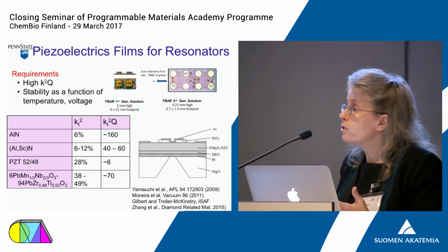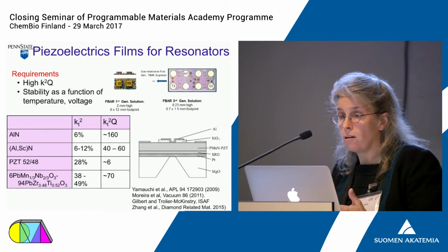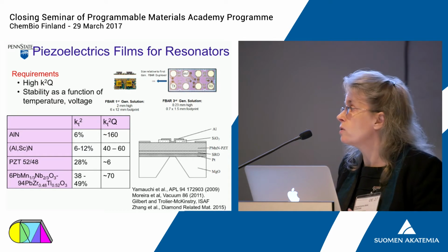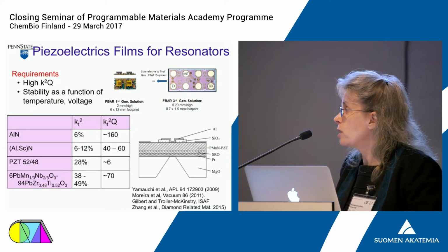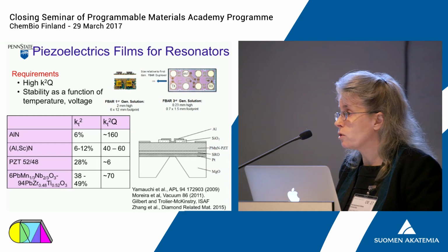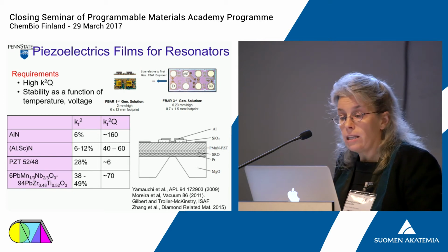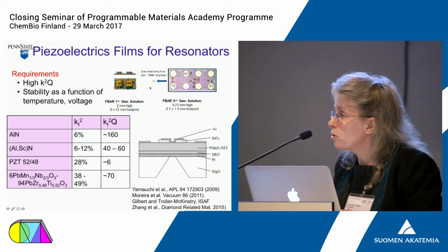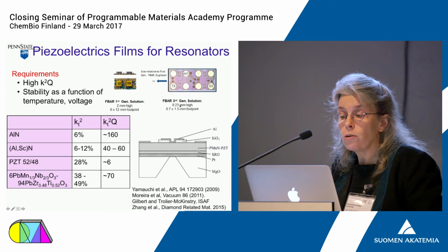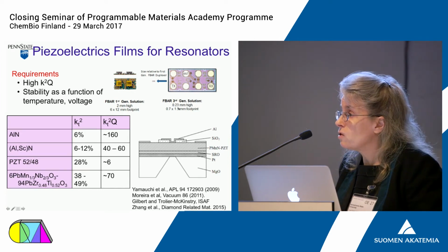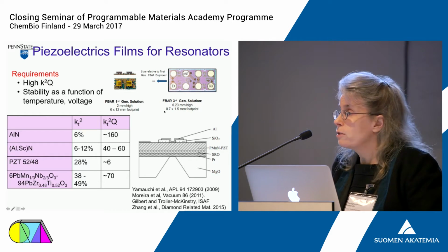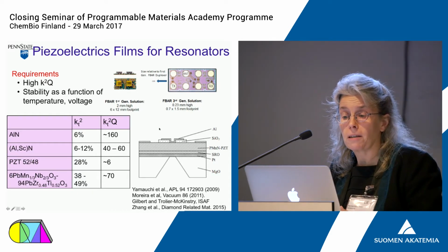And there is an electrical signature of that mechanical oscillation. These are materials that couple between mechanical and electrical energies. That electrical signal and the change in the electrical impedance is what's used for the frequency filtering. And the main advantage is that that is the size of a current generation thin film bulk acoustic resonator. It's on the order of a millimeter in scale and 0.5 millimeter in thickness, and this you can literally afford to carry around in your pocket.